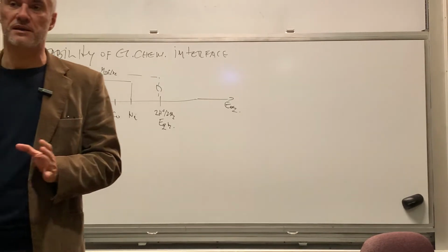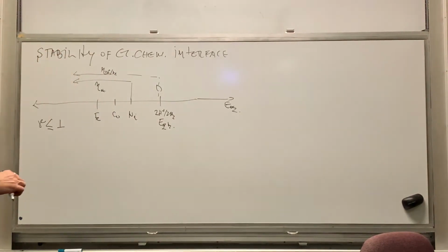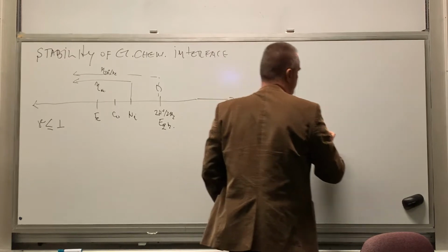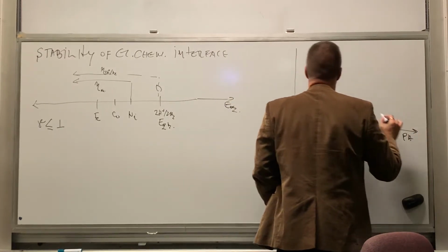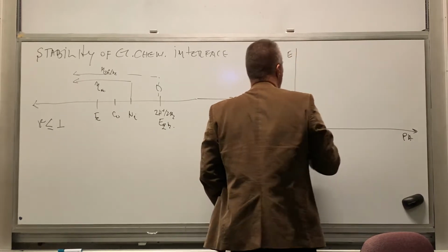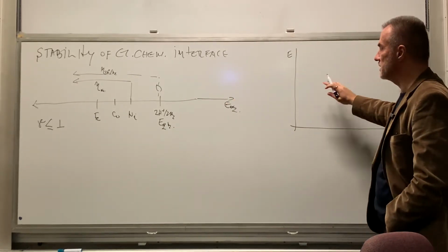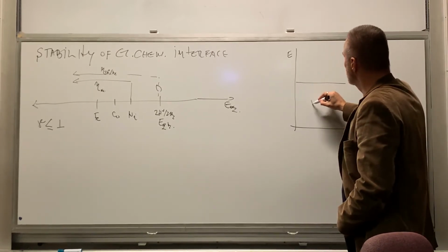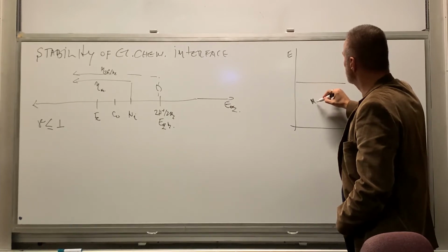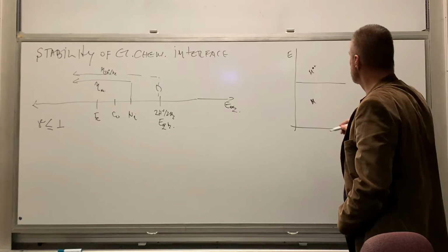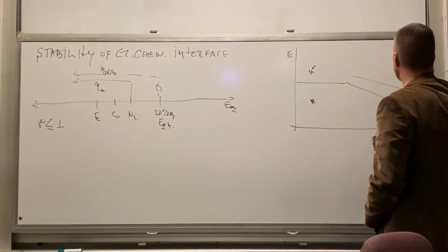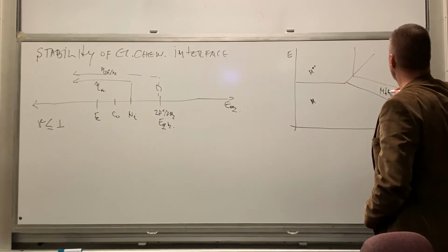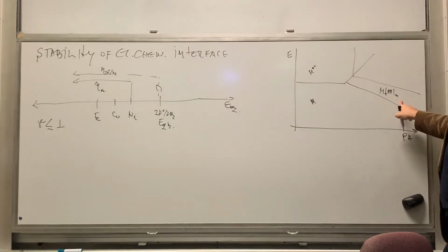Now, that's not necessarily a big deal, but when you talk about iron, cobalt, nickel, and similar metals, the problem is this. If you look at the Pourbaix diagram, what you're going to see commonly for these three metals is that there's a region of, let's say, metal stability, and this is the region of metal-ion stability, and then there's a region here which usually has some different types of things, but here you can see that there is a metal hydroxide stability.